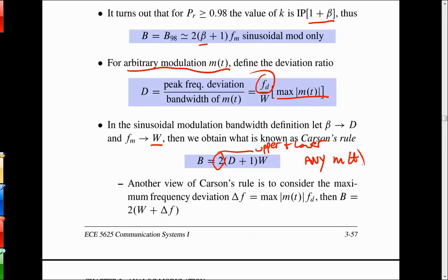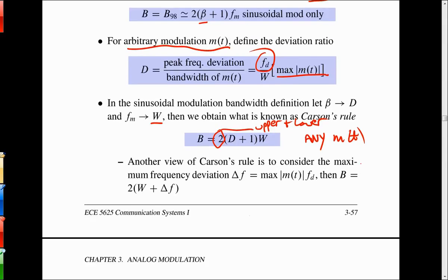The spectrum of an angle-modulated signal is actually a study unto itself. Part of my dissertation involved playing around with developing some results for a particular type of digital modulation, but it's just more complicated. Carson's rule is just a rule of thumb, really. It says the deviation ratio plus 1, times W, and then times 2, is the full bandwidth occupied by the signal.